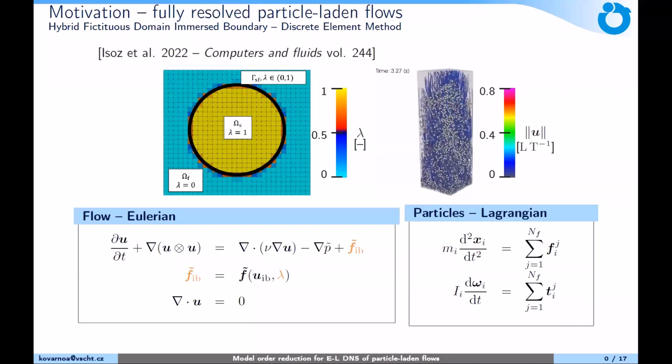The flow is treated in an Eulerian framework, normally by Navier-Stokes equations, and the particles are treated separately by DEM. It works pretty well at this point, but for more complicated cases, it can be very computationally demanding. For example, this case on the right side took about 2 weeks to simulate, so that is quite an issue.